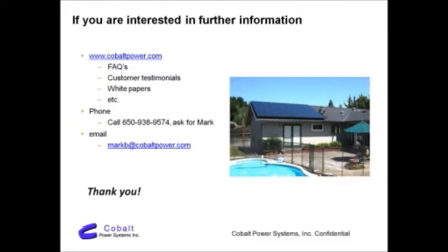to 7.5 kilowatt. And by the way, I just remembered that I failed to answer the previous question about shading. So you really don't want to put a solar array, a PV array, in a location where it has significant shading. Occasional shading, maybe a telephone pole sweeping through the array, or maybe late afternoon or early morning shading is fine, but it's sort of a waste of money to put an expensive PV array in a place where it has significant shading.